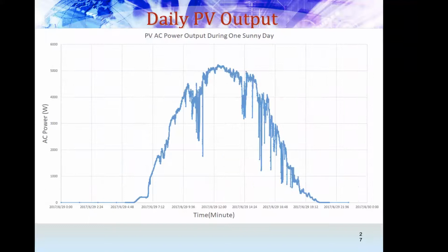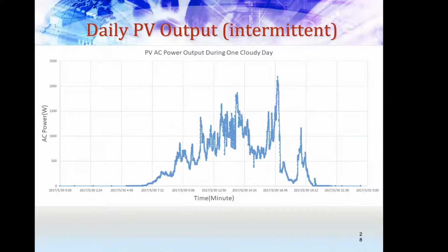Let's look at a day. One typical sunny day with some cloud movement. Cloud movement means you get fluctuations in output. So how do you deal with it? If this is the picture you are dealing with on a regular basis, you can say I'll use some battery to catch these low supply periods. You can do that. That's a good day. This is a bad day, meaning you don't get full output at all, a lot of supply side fluctuations.